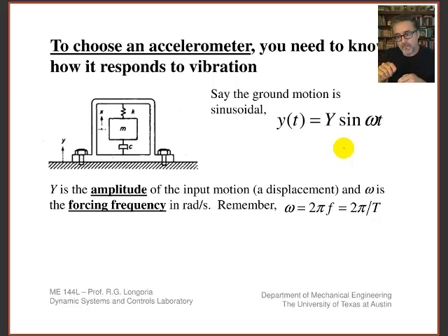That's the key part about accelerometers that you need to understand. When you talk about having a bandwidth of 100 hertz, like the accelerometer we're using, it means the sensitivity is going to be constant up until you get close to 100 hertz. After 100 hertz, it dies off. That's a result of the fact that this system has a real response with a limited bandwidth.